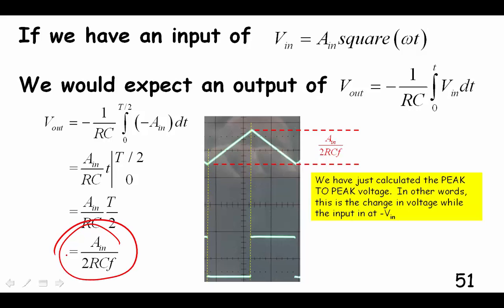So this amplitude here that we're getting, the output voltage, is the peak-to-peak amplitude that we would be measuring. So here's the square wave down at its negative value, and the integrator integrates, and then when the square wave jumps positive, it starts integrating the positive and going negative because it's got that negative sign here. So this amplitude that we found is called peak-to-peak amplitude. It's the distance from the lowest point of the wave to the highest point.